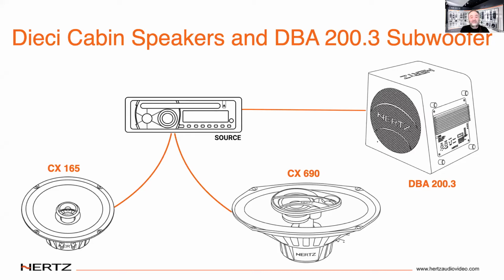And I've also found over the years, customers who thought they didn't get enough bass from their factory system would often turn up the bass tone control in the head unit to try to get more bass. And that would cause distorted sound when the system tried to deliver bass that it just wasn't capable of producing. So ideally, with a system like this, the customer can turn the bass control of the radio back toward the center. And that means you'll have lower distortion on the cabin speakers, especially when the bass hits.